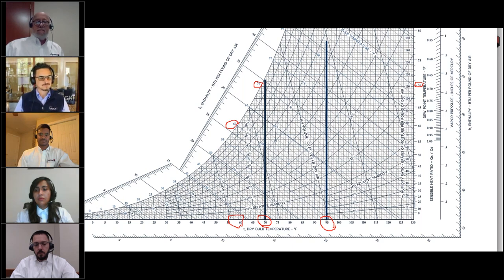Okay. All right, the next two questions, I'll just ask them together and then you can proceed with your presentation. Can you please show us the dew point again on the chart and how many grains in the pound? So I have circled here the 70 degree dew point right here. And I'll state too, not all charts have the same information in the same place. So you might find the dew point and grains on somebody else's chart different than what you find on our chart. So that's 70 there. You can see the equivalent grains is a little over 110, which is right here. So dew point in humidity ratio, otherwise known as grains in short term. I think that answers the question.